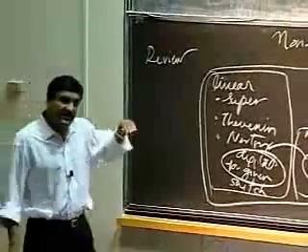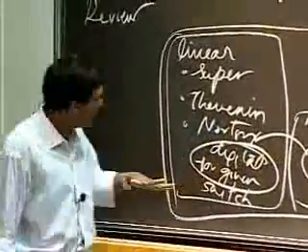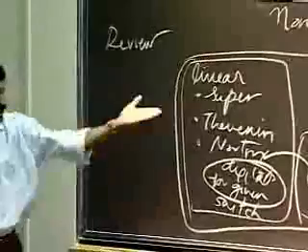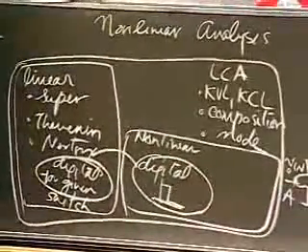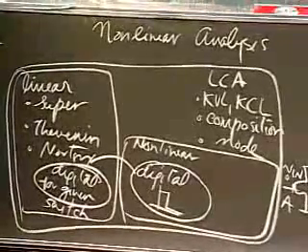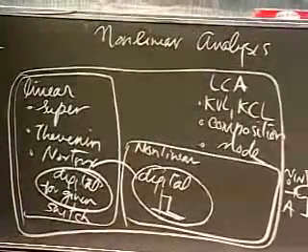Okay? Again, remember, if I fix my switch settings, if I fix the inputs, then the output can be determined using linear techniques, because the digital circuits we're showing you in 6002 simply comprise linear elements like voltage sources and resistors and so on. You'll see some more later, but you can apply your linear techniques and analyze them.